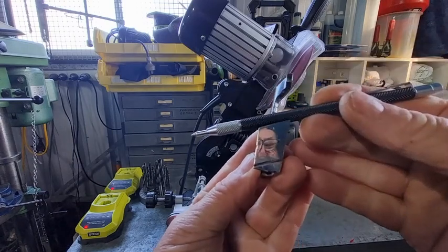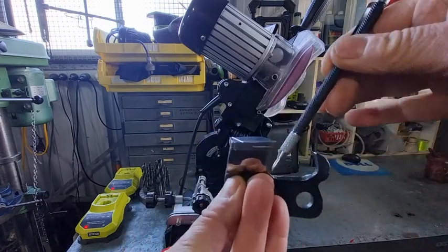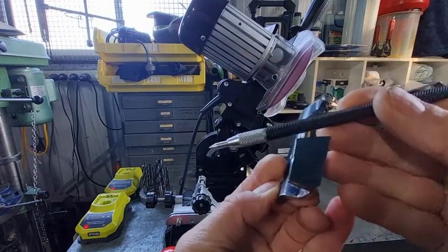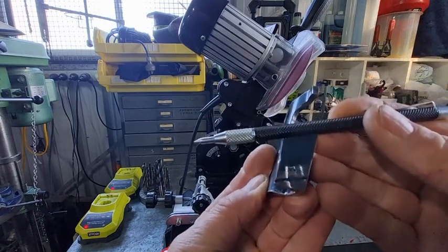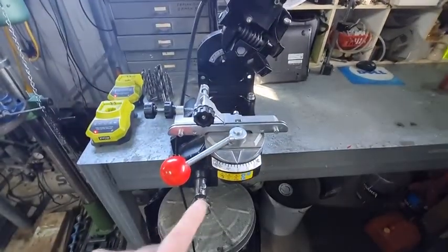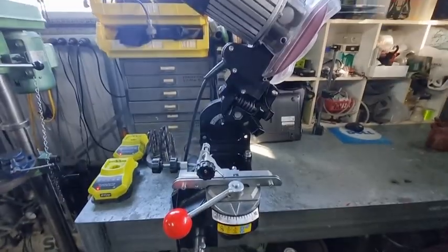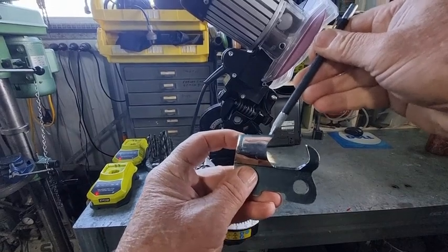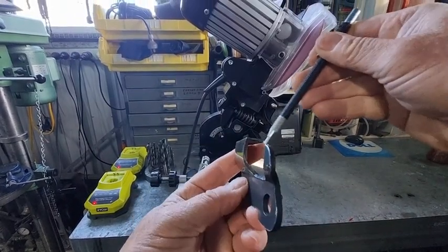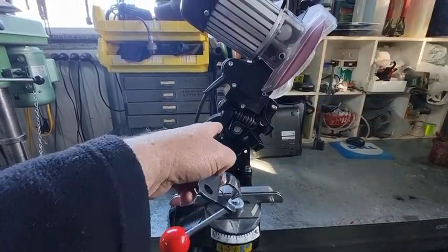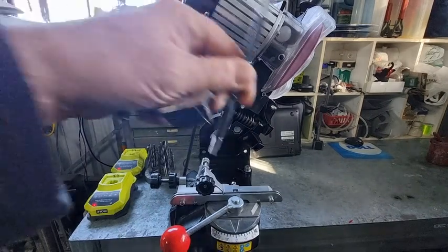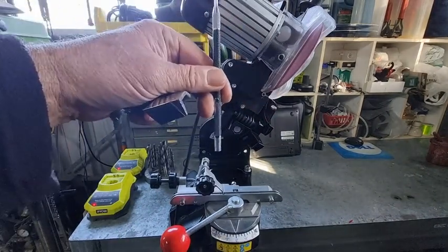This is the top plate angle. This is the top plate cutting angle. The top plate angle here is set by this scale here from 0 to 35 each side. And the top plate cutting angle, which is the angle that the grinding wheel comes on the beveled face, is set by this movable grinding wheel head.